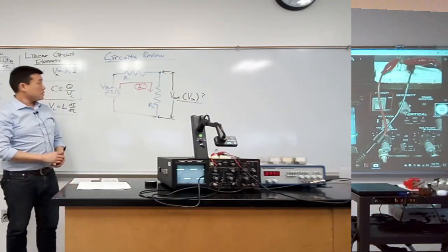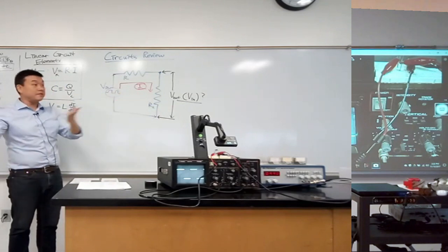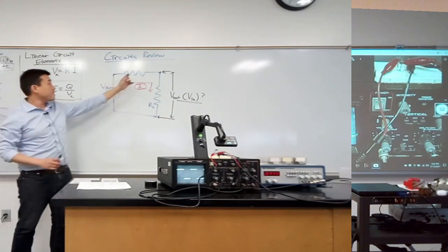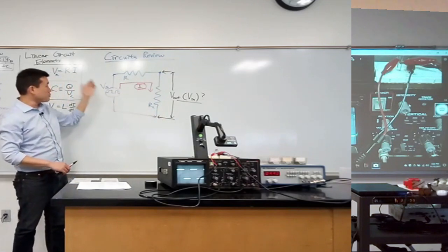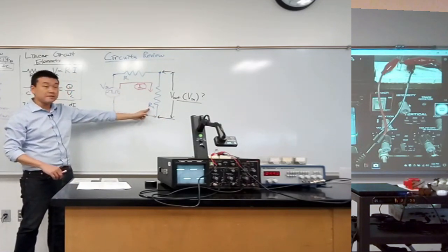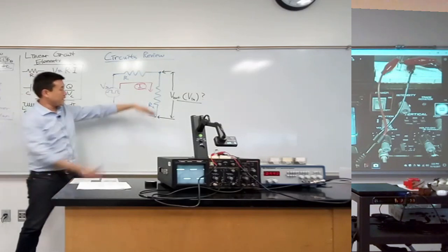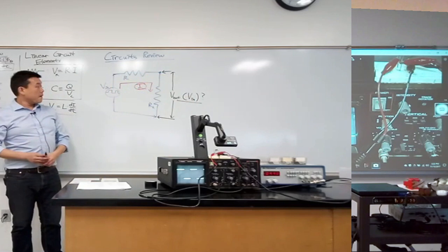Okay? So I'm going to go the long way. So in this circuit, it's simple enough that you can do exactly what Chris was suggesting. Add this in series. That's the equivalent resistance. Or use Ohm's law to find the current. And then multiply this current with the resistance. Then from Ohm's law, that gives you this voltage difference. Right? You all know how to do that.